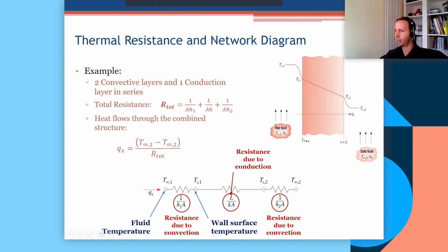So this is a multi-layer wall. I'm now definitely going to introduce the principle of thermal networks. We've done that in second year. You know that essentially you have a temperature difference between two points along your X direction, your one-dimensional representation of space, the line that goes in the X direction. If you have a temperature difference, it's because you've got a resistance to heat transfer.